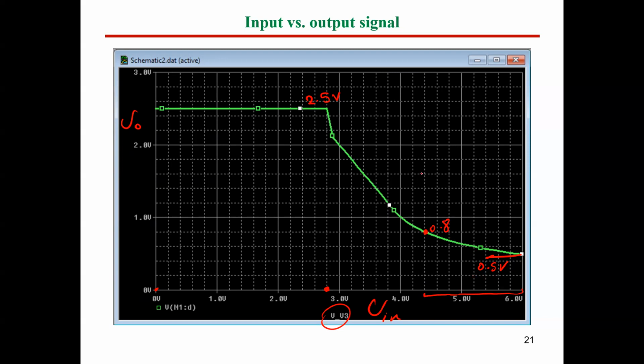Now, guys, I used the IRF150 MOSFET. This is going to be different for another MOSFET. So for that, guys, we said you have to check the characteristic of your MOSFET: what would be the active high range and what would be the active low range when you design inverter circuits. So again, we can say now, in order to be in the safe mode, consider the signal, for instance, from 0 to 2 volt as active low. So all of this as input here. So this is going to be active low in, and this is for sure the output.